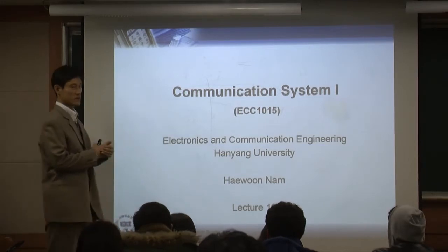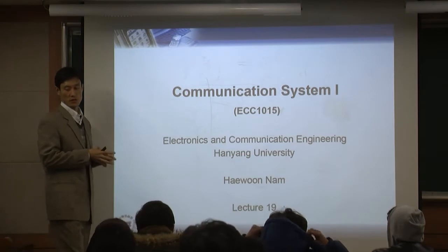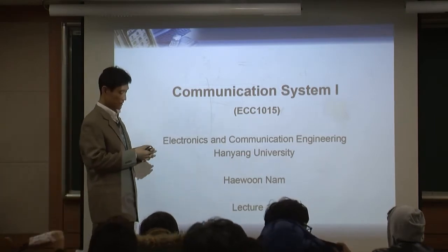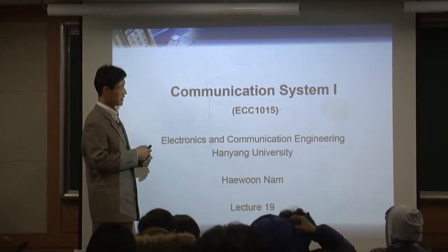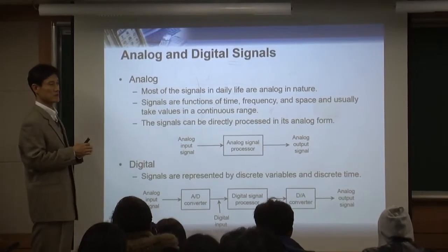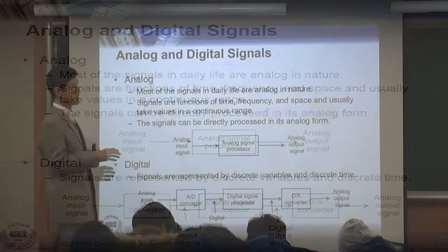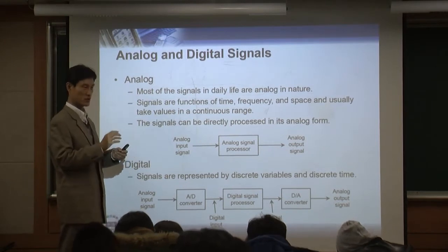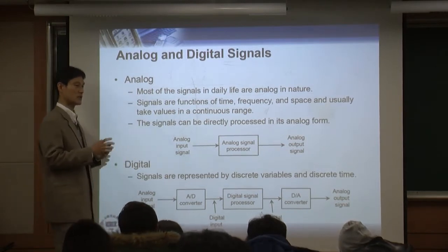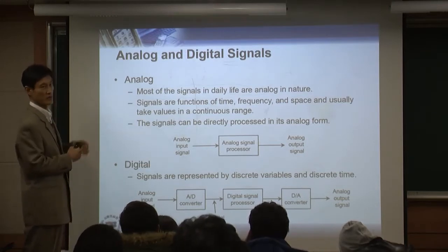Okay. So far, what we discussed is analog, right? We first discussed analog modulation, also analog demodulation. We also looked at what the system performance would be when you have noise, right? Simply speaking, when you have noise in the channel, you always want to measure the SNR, signal power divided by noise power. SNR is the metric that you always use in order to measure the bit error rate and also the performance. So that's the whole story of analog.